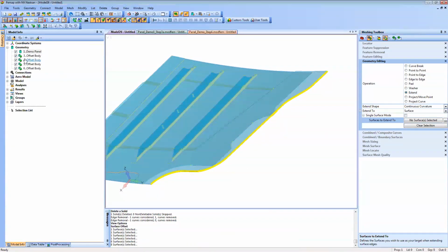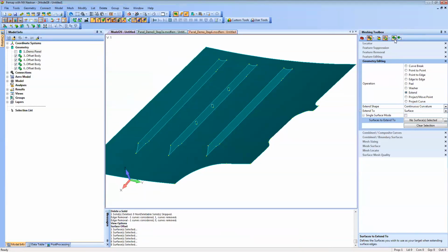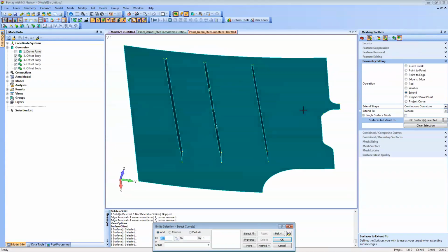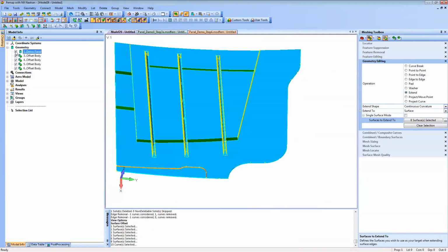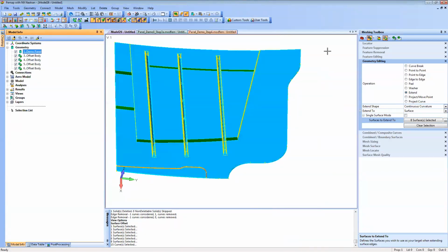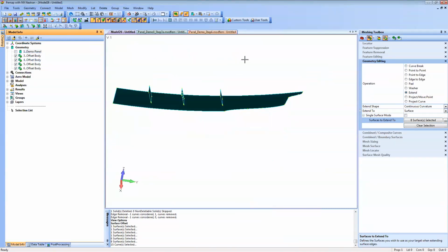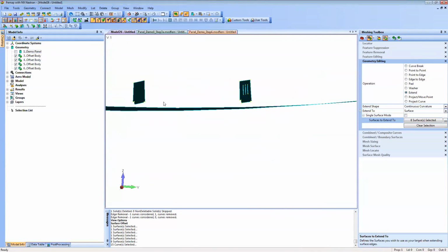So okay, let's hide our 3D solid, then select the surfaces we want to extend. So we can either go to pick box, or you can just do shift and then drag click. So shift, and then those will get us those outer surfaces. Okay, and then there we go. We see how we get a nice matchup at the boundary with our 3D solid geometry and our new 2D surface. So that looks good. The next thing we want to do is we see these ribs that we created.